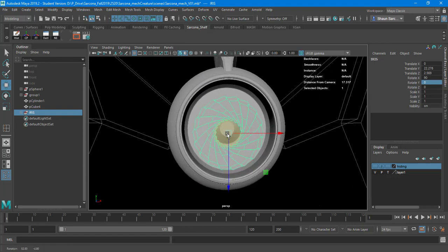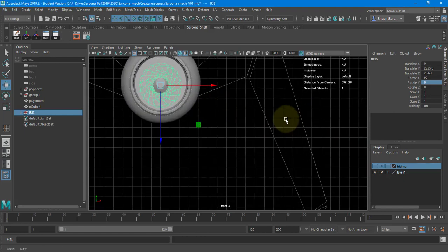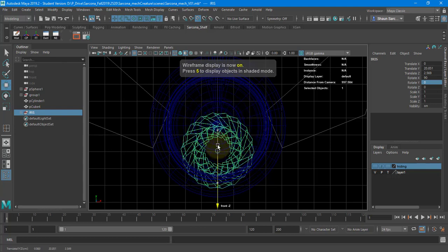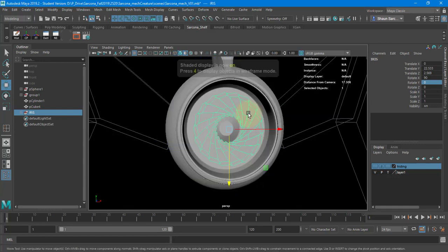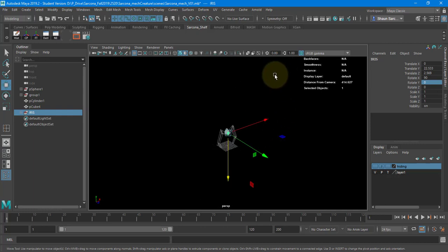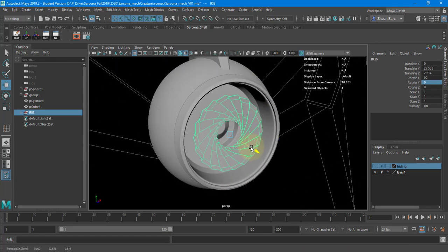And then I can decide where I want this to be. It should be centered, so I'm going to switch to my front view. Go to wireframe, hold down V, and drag this blue arrow up. That'll snap it vertically. That's perfectly centered. Okay. Again, another reason why I keep everything right at that origin, right on that grid line. It makes your life a lot easier. If my robot was way over here, I would have to try to move it, center it, rotate it, whatever else to get it lined up. So I like where that's positioned there. I think that's going to be a good spot.